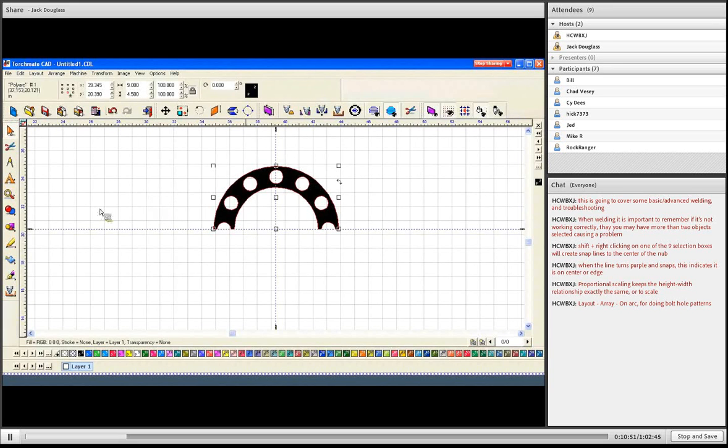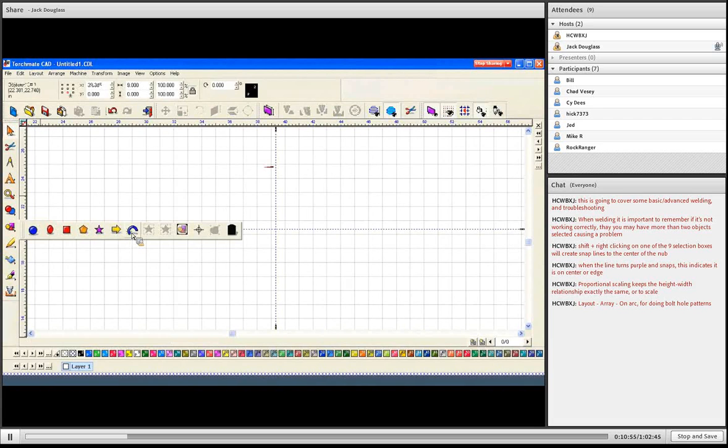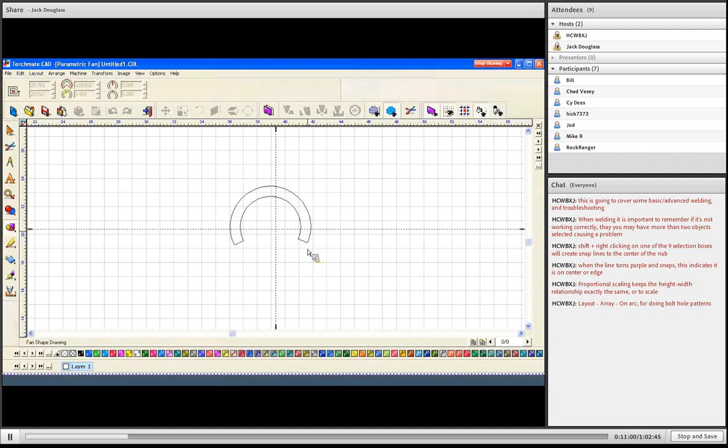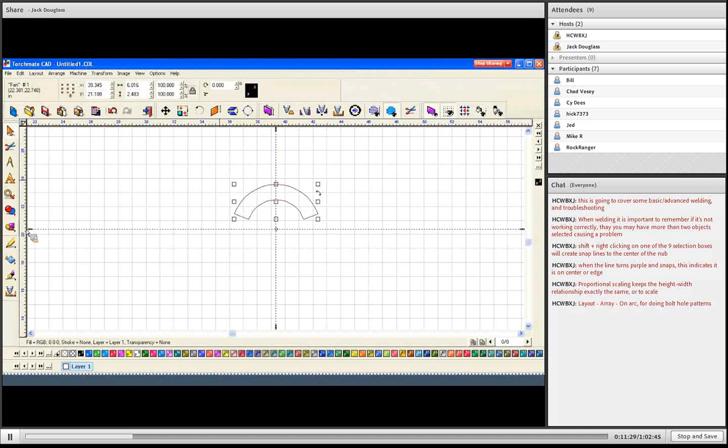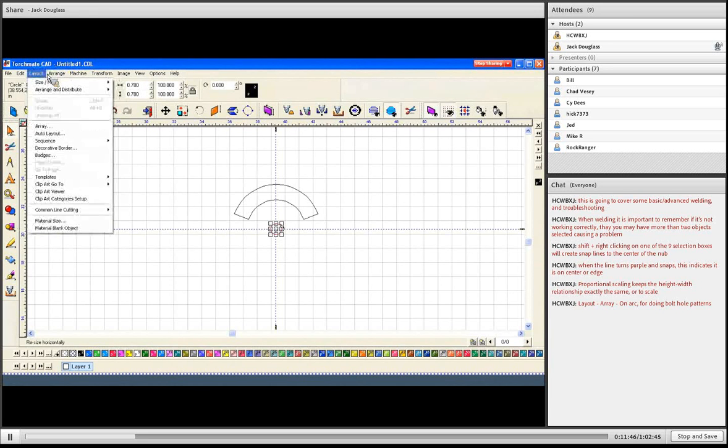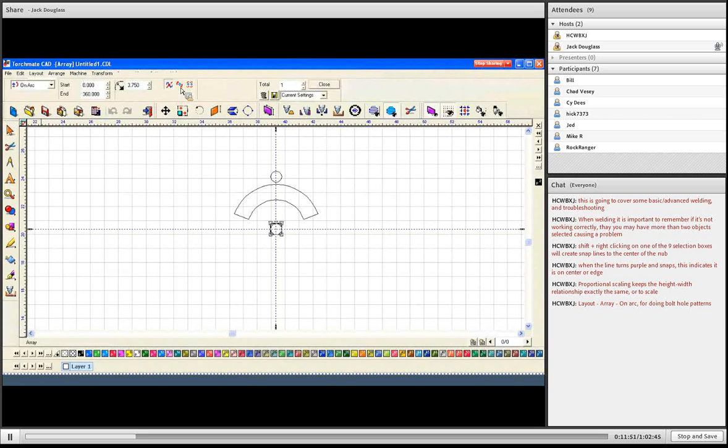Now, there also is a shape tool, it's called the fan tool, for arches. And it's kind of the same thing. We can move this to center on that grid line. And then you can specify the angle that needs to be swept out. So if it wasn't an even cut, say you needed that much, something like that could be set. The angle of rotation will just be set at 0. And then a thickness and also a diameter. I'll do this real quick here so we can move on to other things. But since that's the center of the circle still, when we come in with another circle, we'll make it smaller here. When we come in with another circle to array, it can go around that as well.